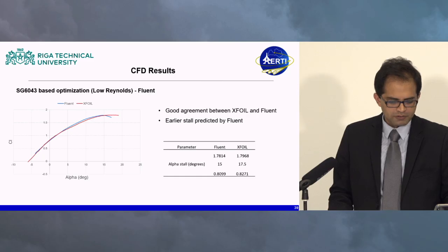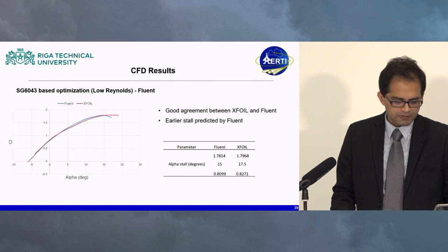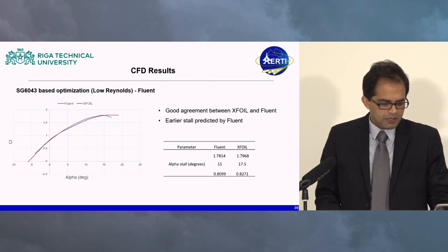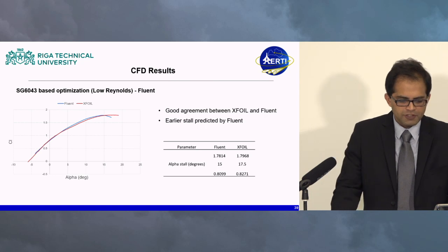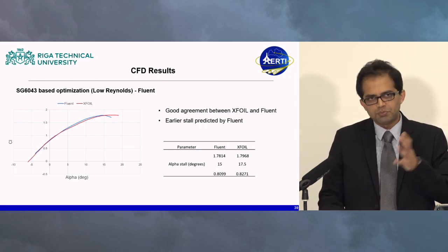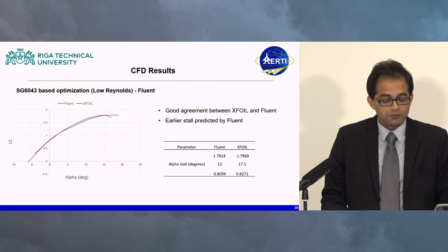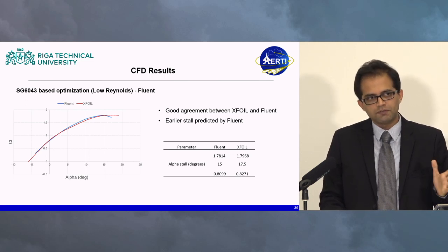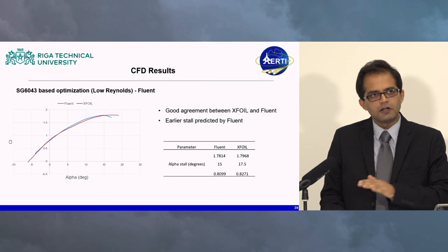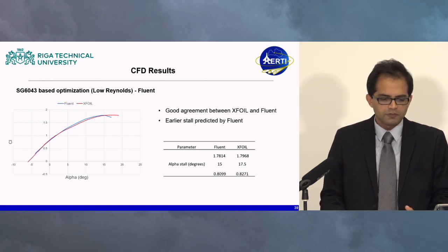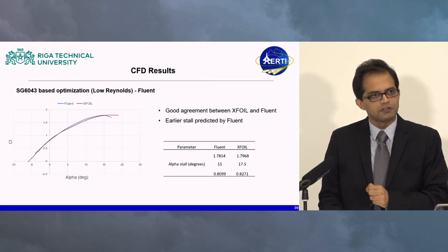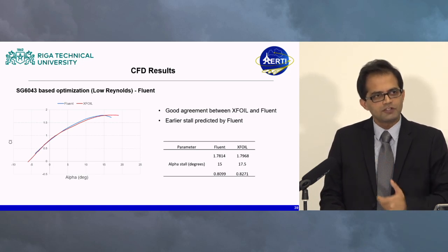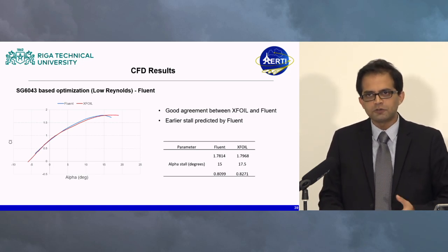Okay, now the same results that we had from X-foil are compared with the CFD results. So the CFD results of the new aerofoil were compared with the X-foil results that we obtained previously. As we can observe, the lift coefficient is in very good agreement in both cases. So CFD results and the X-foil results are in good agreement, and don't forget that these results were matched experimentally as well. So actual data was matched by the X-foil data, and this data is also matched by the CFD analysis as well.